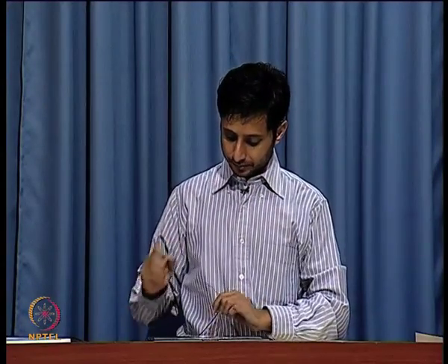Now, source to body and drain to body, these are called junction capacitances. I am just going to discuss these. Source to drain capacitance is of no consequence, because source and drain are really far apart. I have got the MOSFET, the channel is long, source and drain are far apart. In any case, they are not separated by a dielectric material, they are separated by a channel which is conducting, right.